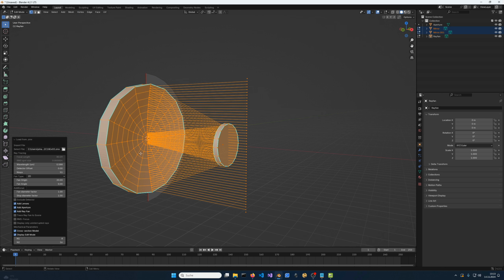And the second aspect is that the primary mirror should have a hole at the center to let the rays pass. So this is also something that explicitly has to be somehow checked, because that's not apparent from the zmx file itself, because optical design is not necessarily identical to mechanical design, and therefore things like these are not very obviously indicated in such a file. And for implementation of this, one would have to explicitly separate these cases. So while the secondary mirror is in the way of the initial beam, it should be interpreted as an obstruction and block the beam, while beyond the secondary mirror, you could think that the software might detect the primary mirror also as an obstacle and obstruct the rays, but in this case, it should be handled differently and a central hole should be generated.